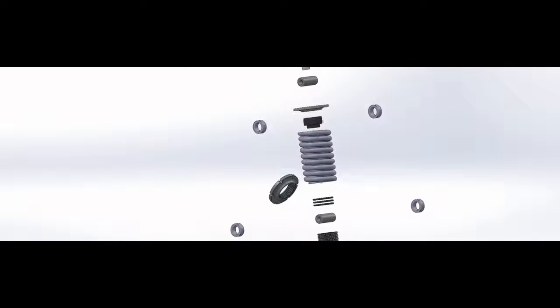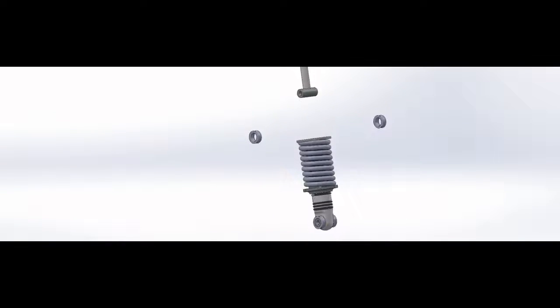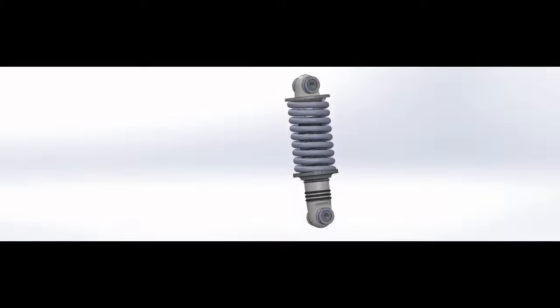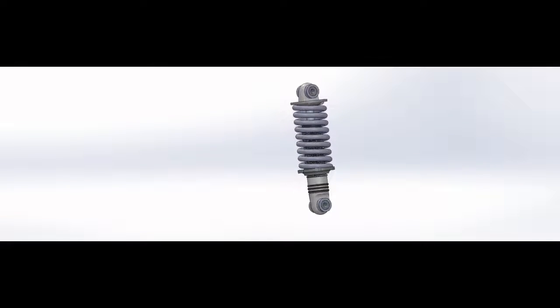Here we have the shock, or in our case a coilover. This attaches to the control arms in the front and rear to give it a point of contact between the frame and the control arm. This video shows the oscillation of the shock. It has a high spring rate to keep it rigid to reduce body roll and sway.